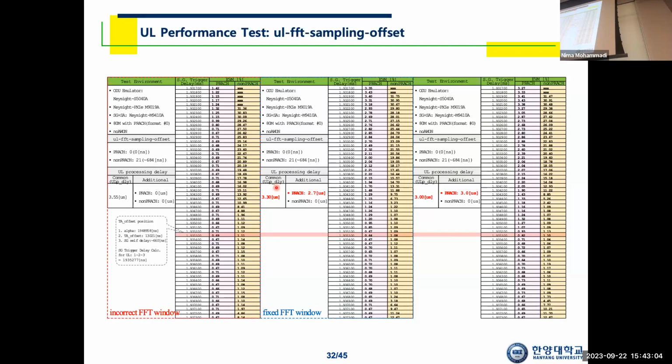Now suppose your radio unit works okay with the downlink packet provided from Keysight ORAN Studio. Now you have proven, as far as you are concerned, that downlink processing is okay. So you provide your radio unit to your customer. Your customer says, oh, it does not work. Then you have two possibilities. Number one, his DU is wrong, but normally that does not take place. Reason number two, you are wrong with uplink processing, which happened to me, unfortunately.